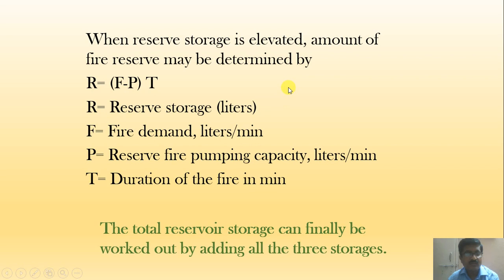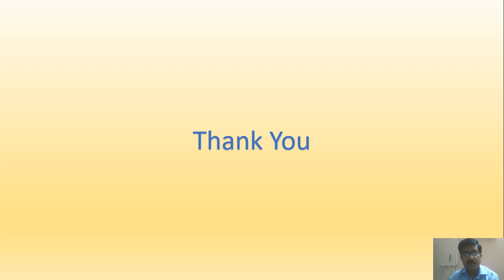So today we have come to the end of this session. Especially today we have discussed the various distribution patterns, distribution systems, and also the types of service reservoirs based on the materials, and also revised some part of the storage system and calculation of the storage. We have also seen how the reserve storage of elevated amount of fire reserve can be calculated. So thank you very much for joining this session.